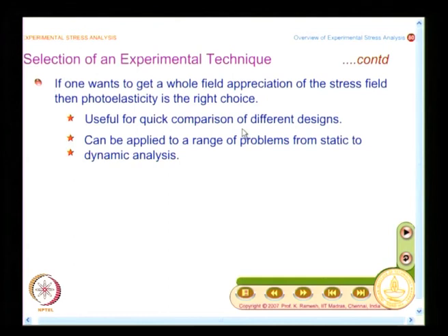I introduced a concept that when you are looking at castings or forgings, I do not have the restriction of only circular fillets. I could relax that and go in for non-circular fillets. And this is one example where, when I have to compare designs, a technique like photoelasticity, if it is possible for you to apply, is a very good candidate. I do not even have to do a quantitative analysis; even a qualitative picture can help you to quickly identify among various options which option is better.